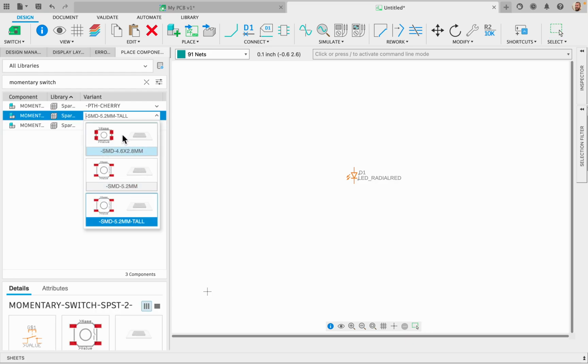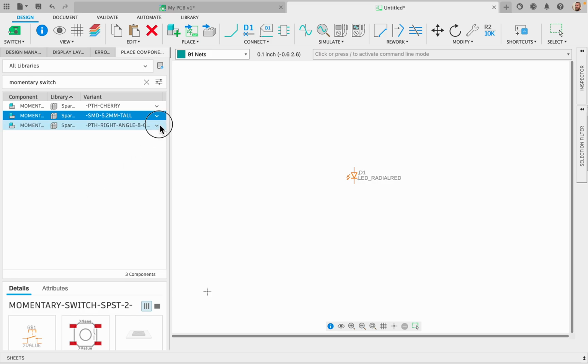Remember I mentioned the red, the green earlier. That's for through-hole components that we've been working with, that we will work with. The red right here is for surface mount, and we're never going to do any surface mount. So if you see any component with red on it, do not use it. You know it's the wrong thing.